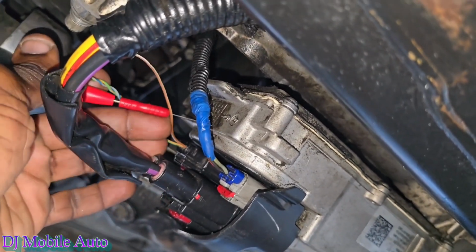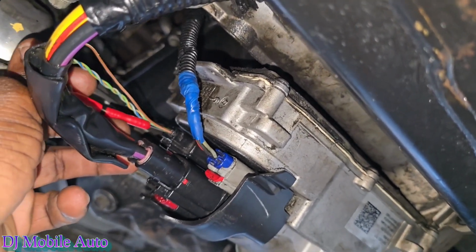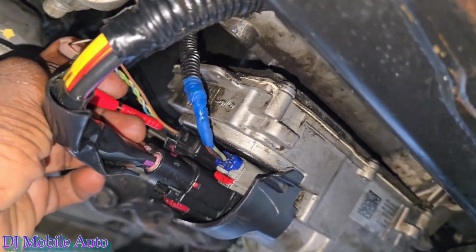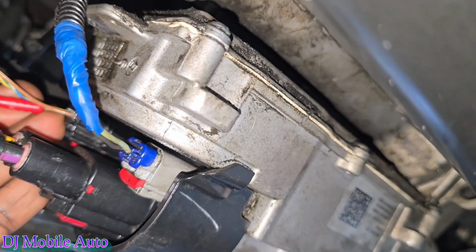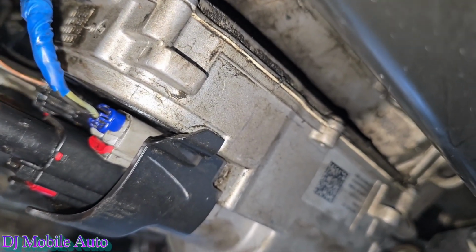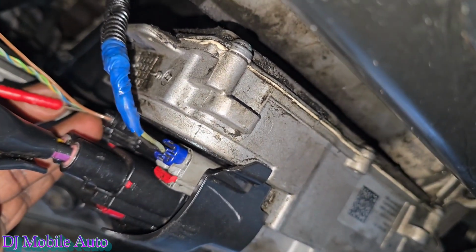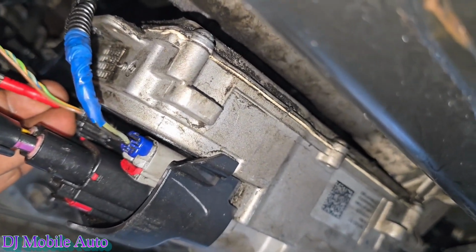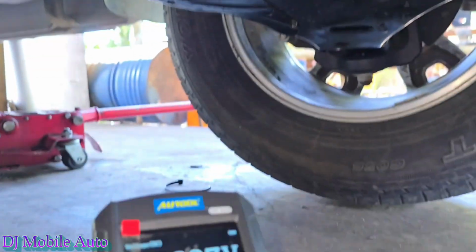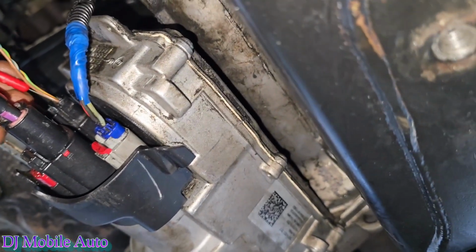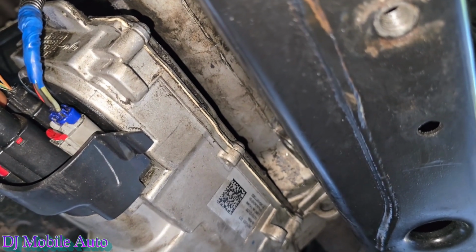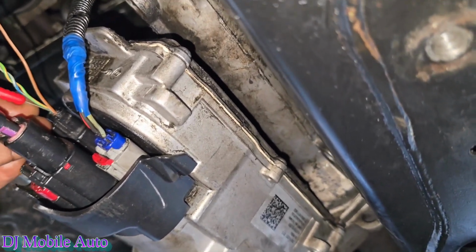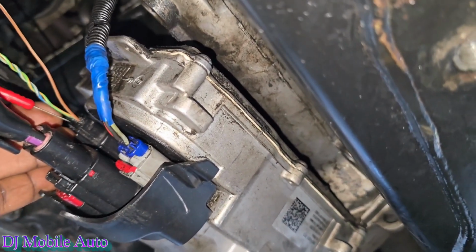And these are the communication line, medium CAN, right? So this is CAN. It's supposed to be like CAN low and CAN high, but the medium speed CAN. Okay, so let's see if we can get access to one of these pins right here. So I'm gonna go into the blue wire with the white stripe. Okay, and let's see what's good. I'm getting 2.3, 2.4, right? 2.24, which is good. That's half of 5 volts. And on the second one, which is the orange with the green wire, I expect to see 2.5 volts. So that's letting me know my communication line is there.